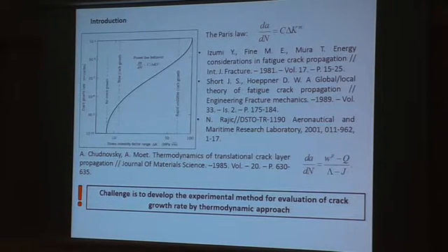I will just present the results briefly. I want to start from the Paris equation and show you some attempts which go near the Paris equation. People try to find other parameters, not the stress intensity factor, which describe the velocity of crack propagation. Of course, from a physical point of view, the stored energy is the best value to describe the crack propagation rate. We know the value of energy which is needed for crack advance. And it's interesting to measure: is it possible to measure this value or not?